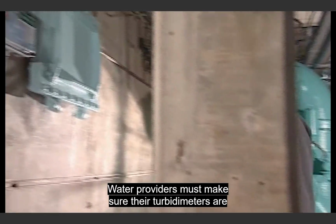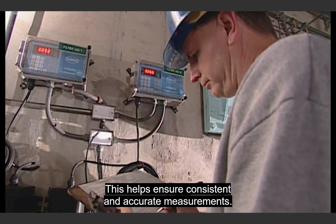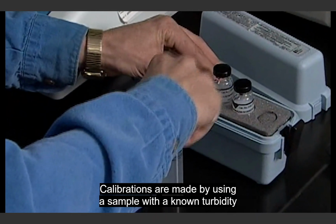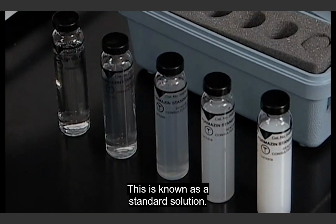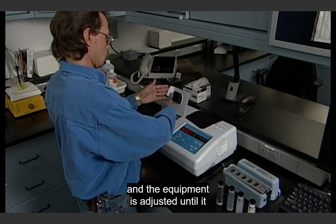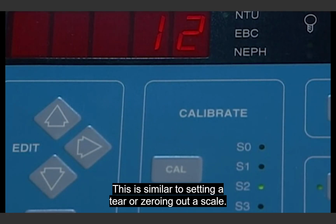Water providers must make sure their turbidimeters are properly maintained and regularly calibrated. This helps ensure consistent and accurate measurements. Calibrations are made by using a sample with a known turbidity level. This is known as a standard solution. The standard is placed in the turbidimeter and the equipment is adjusted until it gives a measurement equal to the turbidity level of the standard. This is similar to setting a tare or zeroing out a scale.